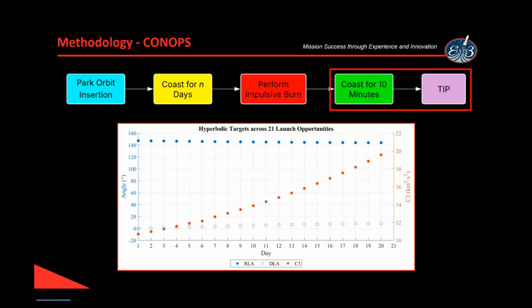But if you're in a polar park orbit with an MLTAN of 0600 to 1800, that means the orbital plane is going to be normal to the sun vector. So you're just always going to be blasted by the sun for the entire duration in that particular polar orbit, as opposed to a 28.5 degree orbit where you're going to be eclipsed by the Earth for part of each orbit. So I think that's what he's getting at there. But again, that's not my specialty by far.